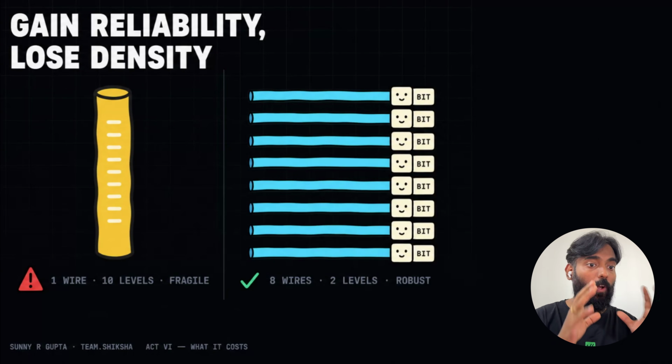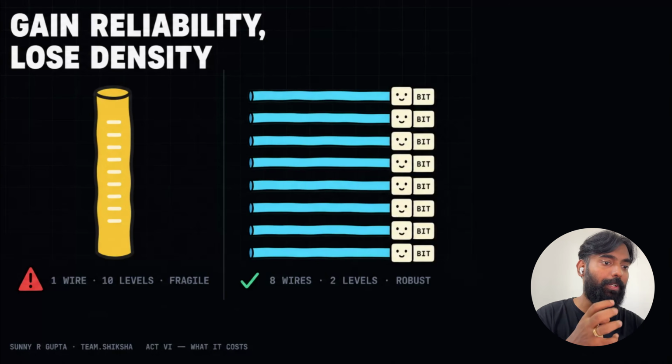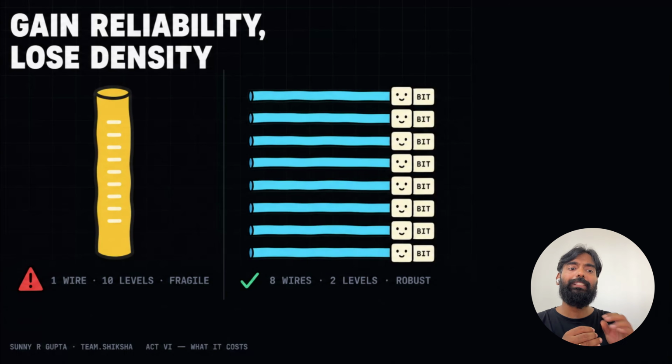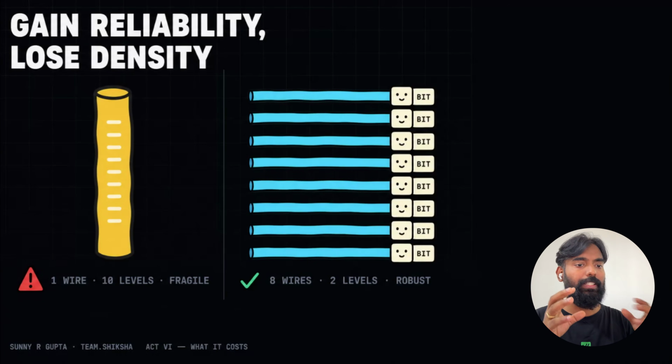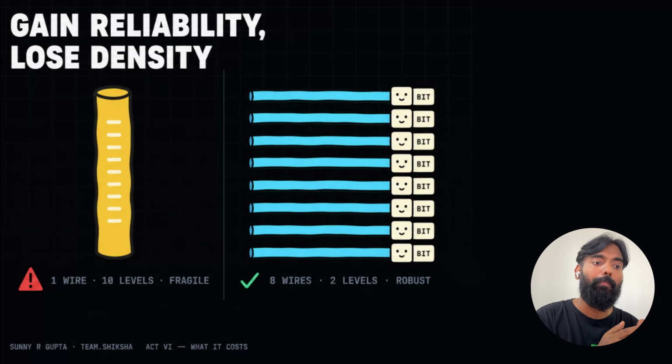So here's the takeaway. Computers use binary not because 2 is a magic number, but because the physical world is noisy and 2 states give us the maximum margin to tell signals apart. Every gate regenerates the signal, erasing noise at every step, and we group bits into bytes to build meaning on top of that reliable foundation.